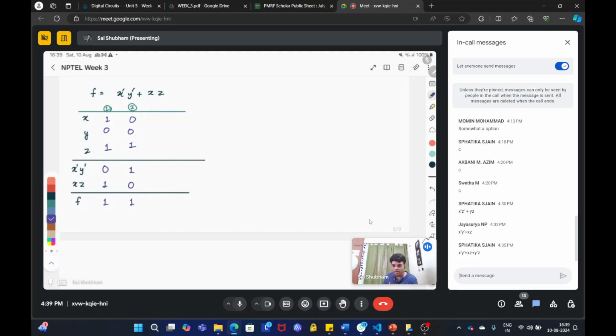So earlier I mentioned that there will be some glitch, but right now you cannot see the glitch. The reason being that we are assuming that whenever there is a transition in x from 1 to 0, your x bar will immediately transition from 0 to 1.